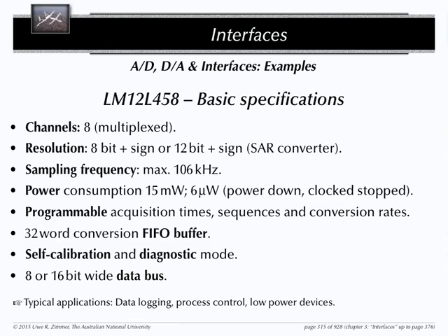It frees up time on the CPU to do other stuff, and you let this run in the background. For example, if your sampling frequency is much lower than the clock rate of your CPU, say a few hundred kilohertz, that takes a long time from the perspective of the CPU to even do a single conversion.